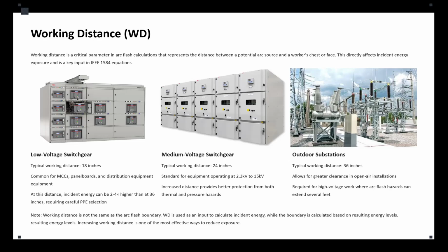So, what is actually working distance? Working distance is defined as the distance from the prospective arc source to the worker's chest or face, the part of the body most likely to be exposed to an incident injury during the fault.